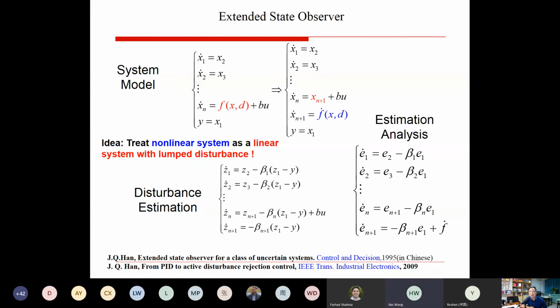But for our DOBC on the nonlinear control framework, it's easy to understand if you are good in math and theory, and you just need to do some simulation and know the parameter tuning rules. And I think you can work well. It's always better than PID, and it also includes the nonlinearity modeling and the cancellation. I think in most cases, both strategies work well, and combining these two together should be better